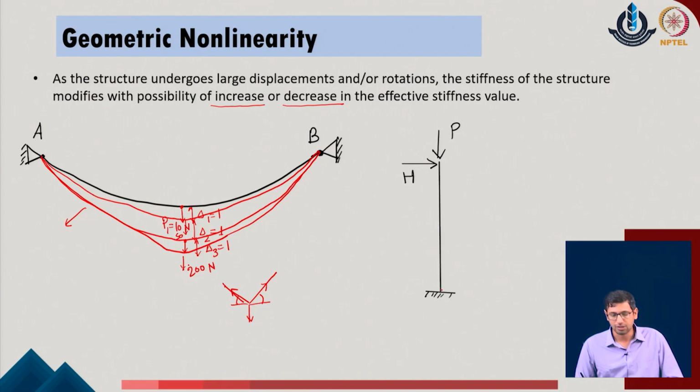What typically happens if we have a lateral load which is also active along with the longitudinal or compressive load on the given system, is that the system will undergo some amount of deflection, and some amount of lateral deflection will appear like this. So, if I say that the system has moved by some amount of displacement in the lateral direction, say the delta value, now the load which was active on top of the given system will also be applied over here.